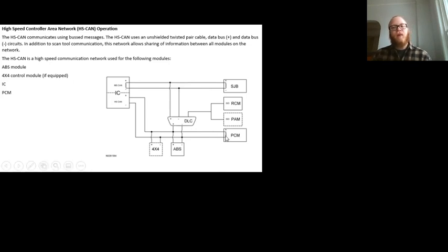For the PCM, however, if it takes an extra couple milliseconds to open up that fuel injector, well, the timing may have already passed. Think about how fast a crankshaft is moving and how quickly valves open and close. If it's trying to open the fuel injector at the right time, but we've got a window of a few milliseconds on either side of it, well, we've just kind of ruined the entire thing as far as drivability goes, and emissions are completely out the window at that point.